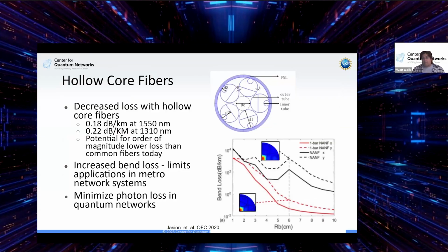All right, and then lastly, we have hollow core fibers. These hollow core fibers have a lot of the same properties as normal fibers. It's the same general shape. The only thing is that this one specifically uses an inner and outer tube geometry, and so it's a much more complicated process. We won't be covering that here. The main idea, though, is that if we go back to our ideas of total internal reflection, that still applies here.